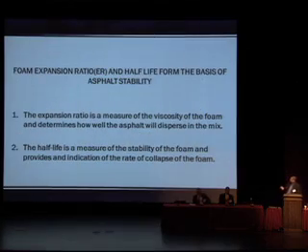Okay, so the two things you looked at, I pointed out to you there, were the expansion ratio and the half-life of the asphalt. The expansion ratio of the foam is a measure of the viscosity of the foam, determines how well the asphalt will disperse in the mix. The half-life is a measure of the stability of the foam and provides the indication of the rate of collapse of the foam.